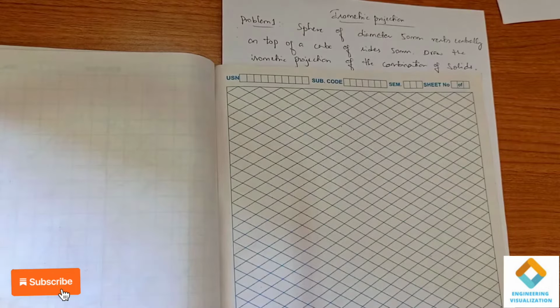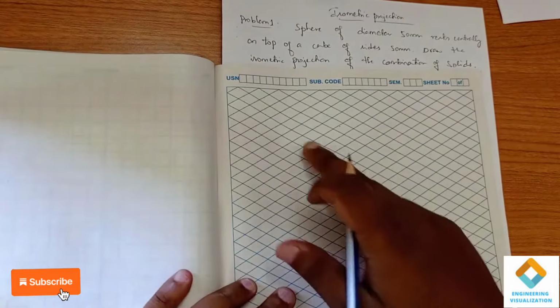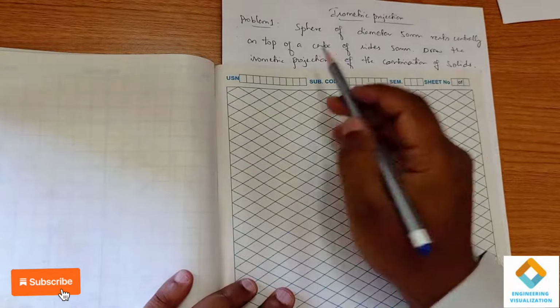Okay, today we are going to start isometric projection. Isometric projection is nothing but a projection of a solid or a combination of solids by projecting at an angle of 30 degrees here. You can see here we have 30 degree inclined lines. Using these lines we have to do the isometric projection. So in this isometric projection, we see the first problem.